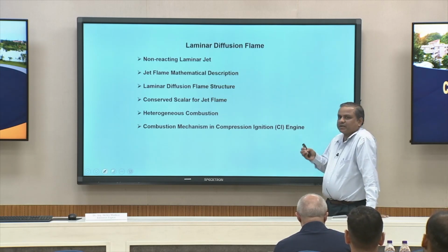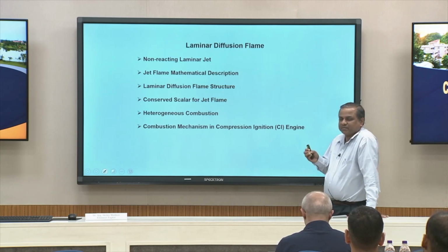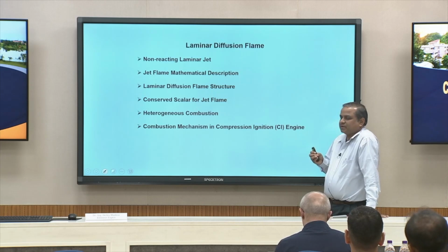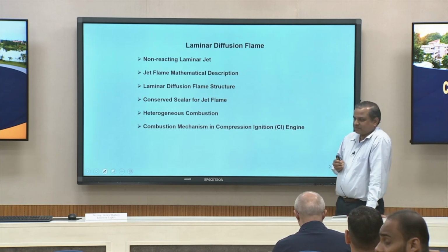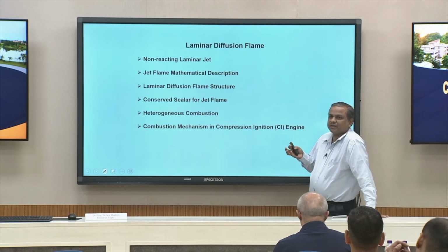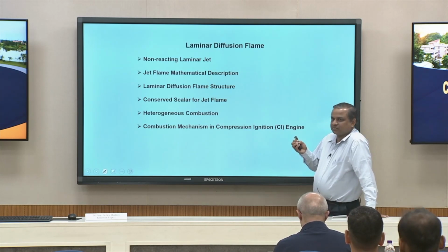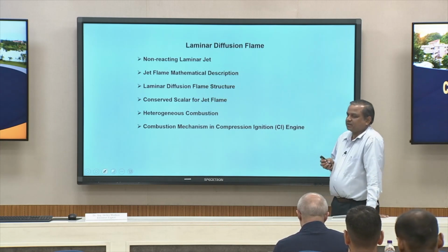Next, where we get such situations with laminar diffusion flame: you can recall that in combustion in compression ignition engines, we spray a fuel jet through a fuel injector into air which is already at elevated pressure and temperature in the cylinder.